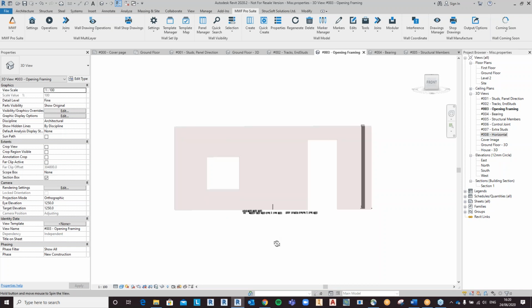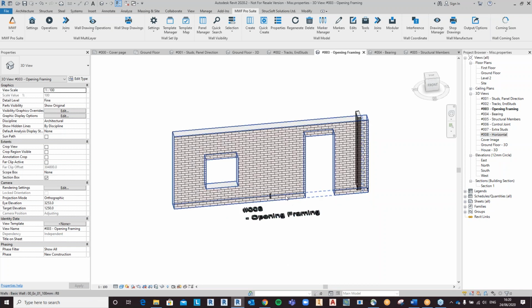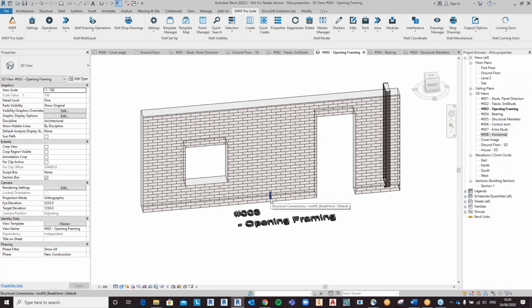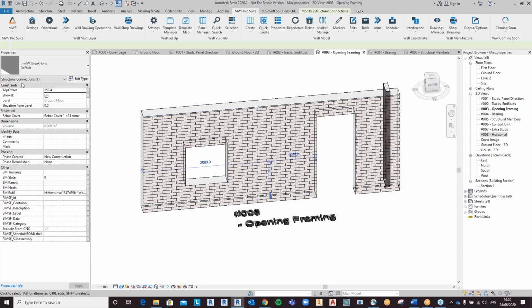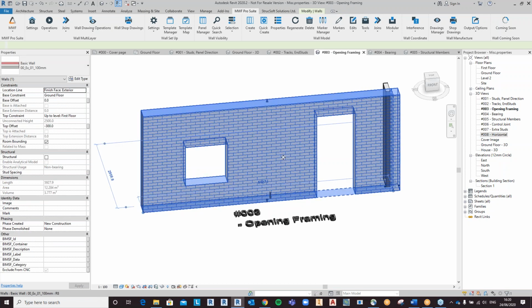So the way this wall differs from our other walls, I've actually used Revit splits on the other panels, which you may be familiar with. However, in this one, I've decided to use our MWF break horizontal marker. So when I place this in my architectural wall, it keeps it looking aesthetically the way we want. However, once we create a panel, we have that split that tells us that we want a panel on this side and a panel on this side, and they should be treated independently.